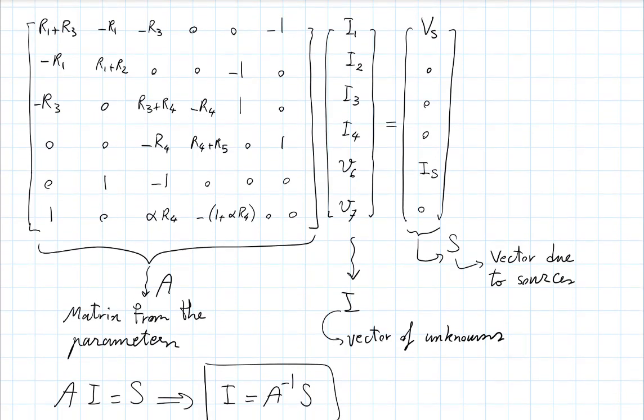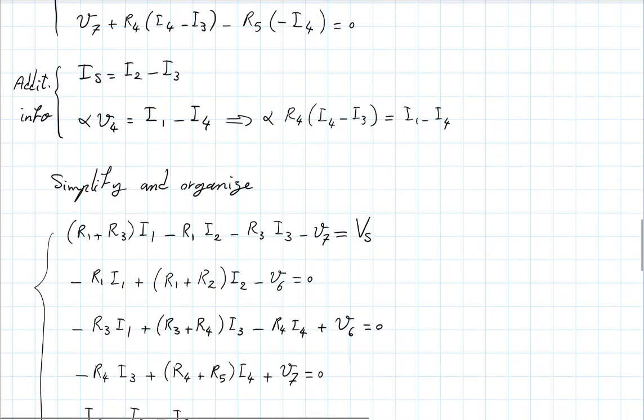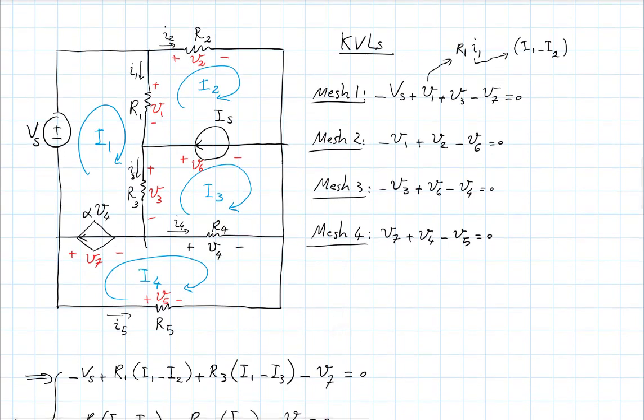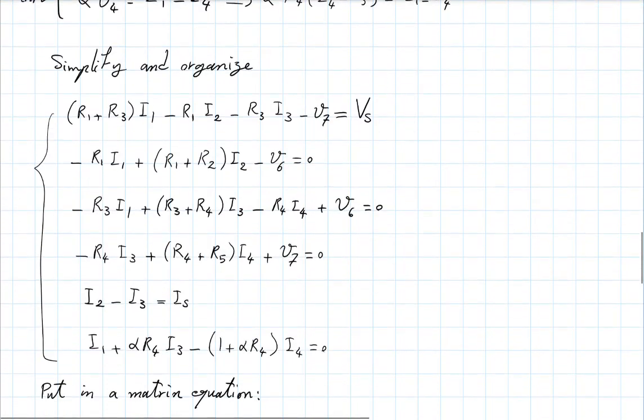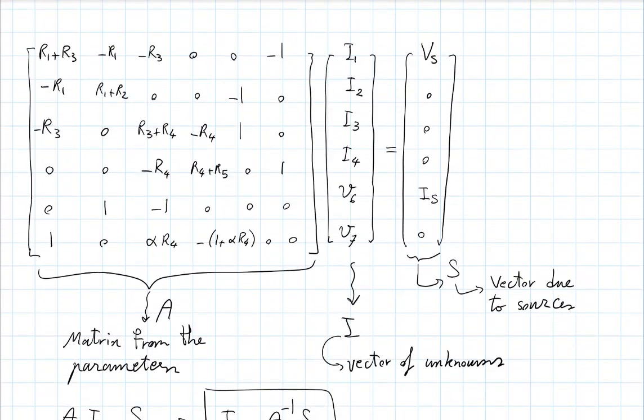And again, as you see, similar to what you saw in nodal analysis, the matrix is not too bad. It's relatively sparse. That's because if you think about where each equation comes from, it's a KVL, and each KVL contains only a few of the elements, typically. So it doesn't contain all the mesh currents, and hence a lot of the zero coefficients in the matrix. And that's good from a computational point of view.